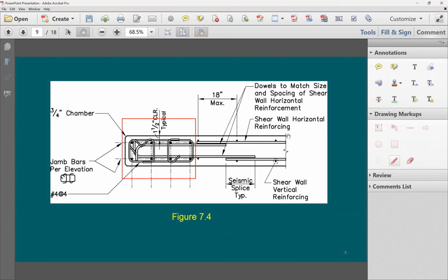The shear wall height is 16 feet and the width is 10 feet for the length. Width or length is the same. Now this is going to be controlling my shear factor. 16 divided by 10 is going to be 1.6. And they ask, what is the minimum reinforcement? It's true that it just says the minimum reinforcement, but you have some shear demand that you need to check the shear strength for.